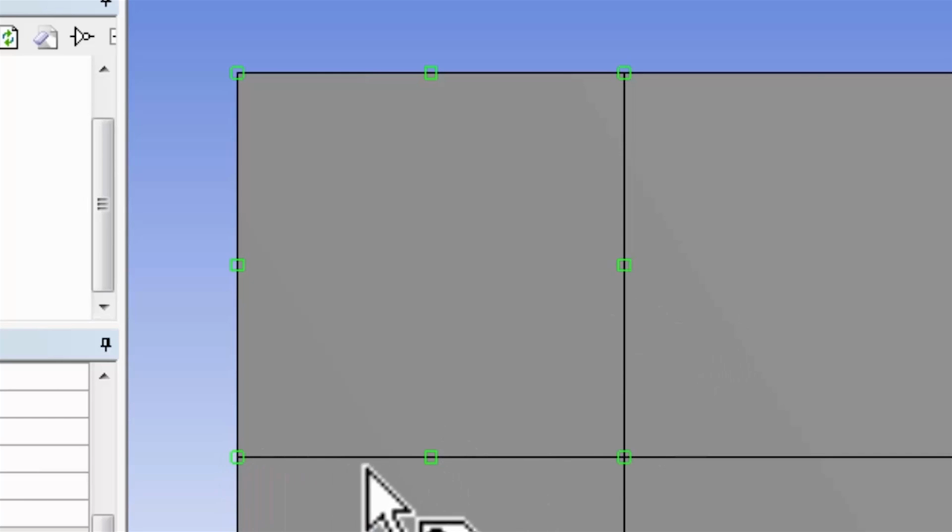This means that when it writes interpolation in this direction, it can use a second order interpolation. When it writes interpolation in this direction, it can use a second order interpolation. So we have second order interpolation in 2 directions, and so it's going to use the second order interpolation, and we can confirm that when we actually get the solution and see what element type it's used.